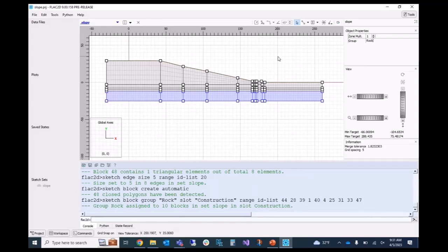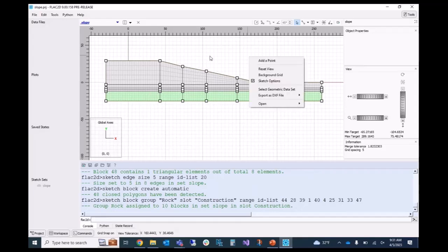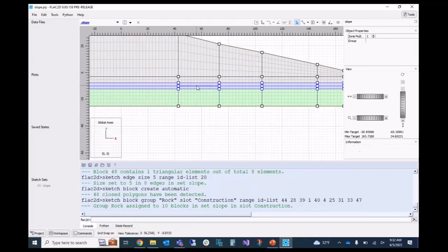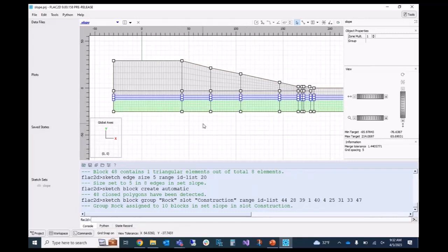And then the next 2 layers are the clay. Remember, we had to draw that extra line to demarcate the bottom of the slurry wall. But in fact, these two layers are both clay. So if you can try and do the same thing, draw a box around these two layers. Zoom in a little bit here to make sure that you've selected them. They should turn blue.